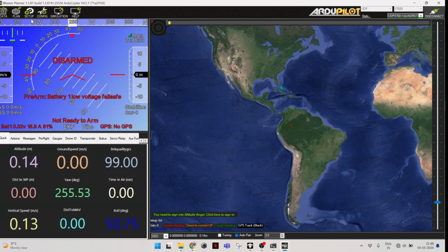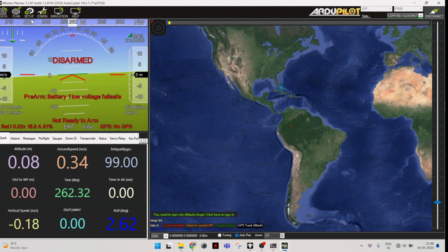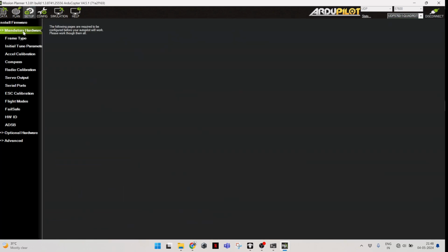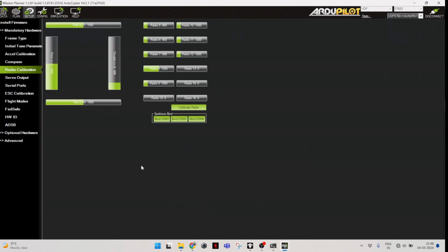Okay, so let me just keep my flight control system here. Now let's go to the setup, just check if we are receiving the RC or not. Yeah, let me test it. Yeah, so finally we have RC. Okay, and the connection is on UDP. Everything is working fine. All the parameters have already been loaded. That's how I actually connected through MAVLink.